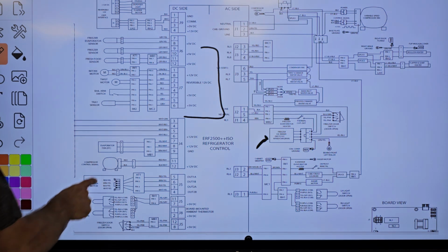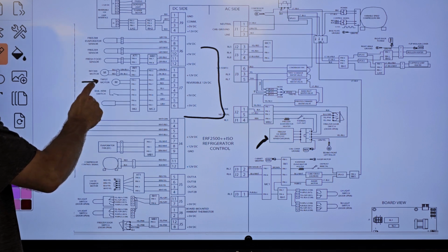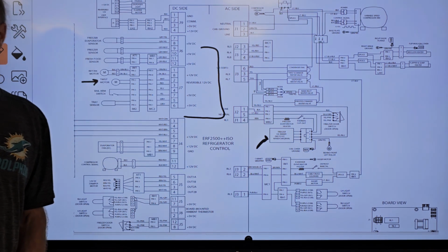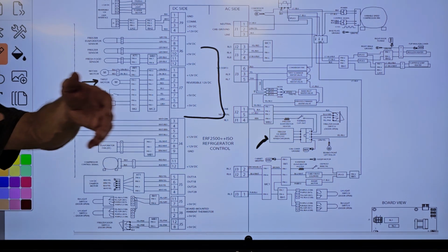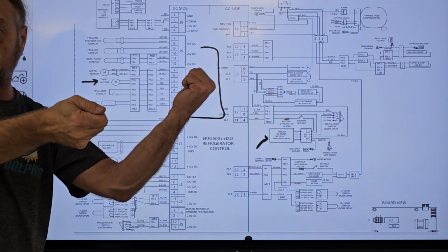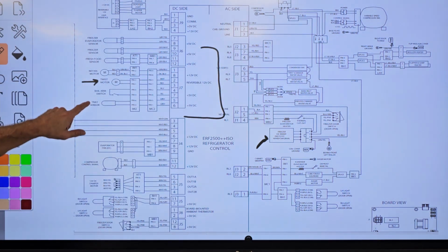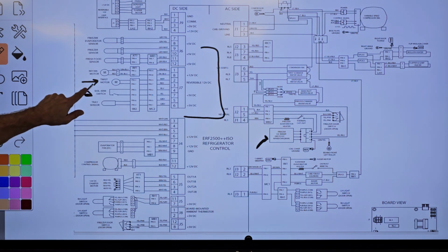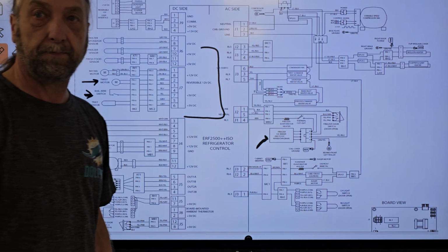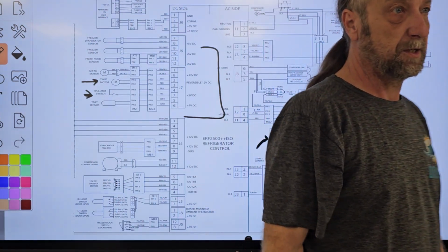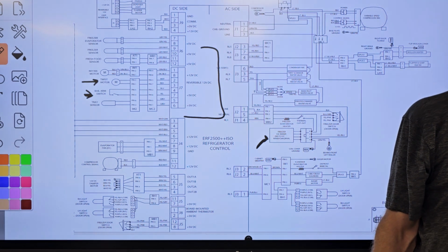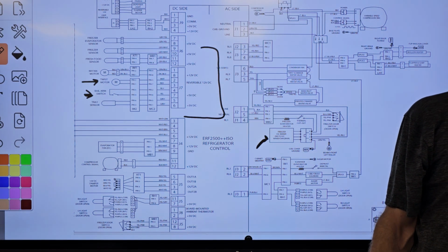We have the twist motor, which is the actual motor that twists the plastic tray, and then the tray twists and the ice falls out. We have a bail arm switch. Does anybody know what a bail arm switch is? The bail arm switch is a switch that's connected next to the flex tray. It basically tells the machine when it's full.